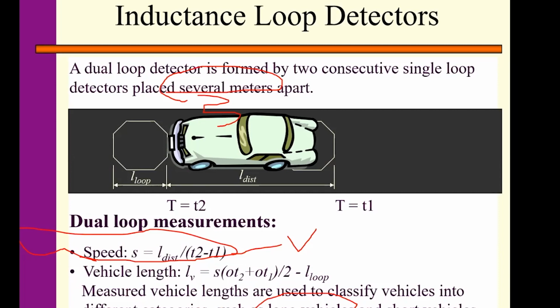Sometimes it could be the 18-wheel trucks. The reason we want to distinguish short vehicles and long vehicles is that the impact of those two vehicles on the pavement is quite different. You know, the pavement is damaged by the vehicles. Here in Honolulu, I think specifically, the pavement needs to be resurfaced every 6 months or 2 years, depending on the location.